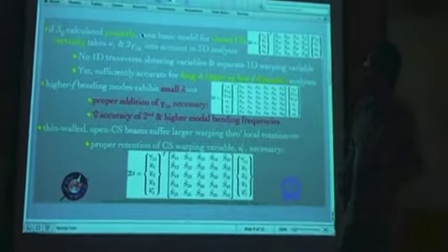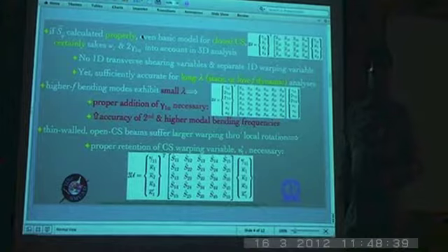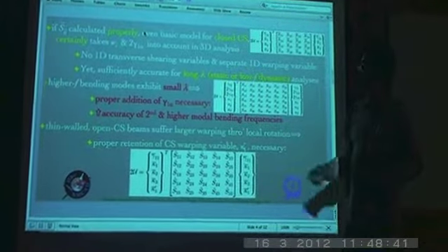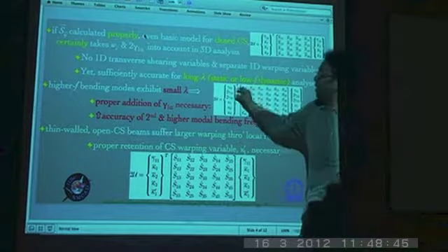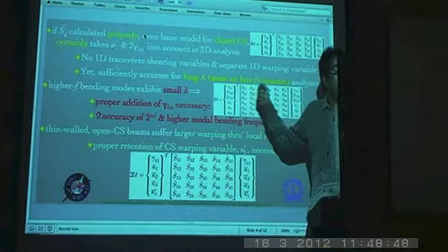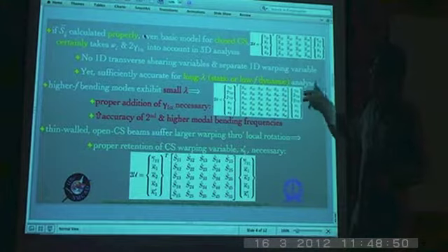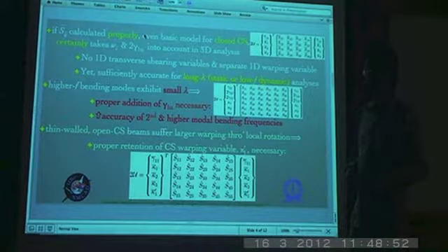But when you want to go for high frequency dynamics, basically where the wavelengths are much shorter, then it is preferable to go into the 6x6, primarily to extract the additional information that you want, specifically in terms of the transverse shearing rotations.